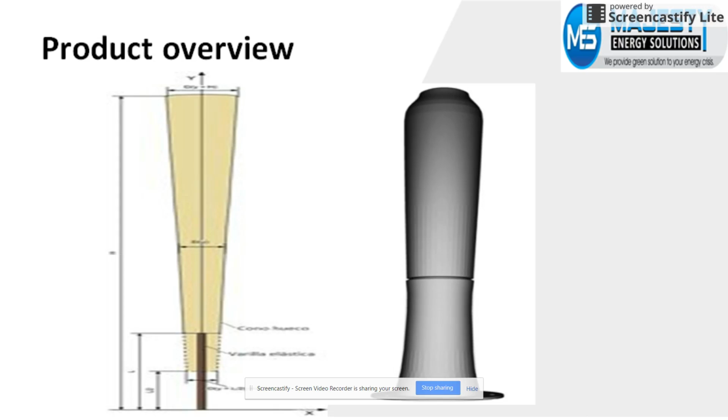The structure is built using resins reinforced with carbon and/or glass fibers, materials used in conventional wind turbine blades. The inner cylindrical rod, which may penetrate into the mast for 30% of its length, is anchored to it at its top and secured to the ground at its bottom part. It is built with carbon fiber, which provides the highest resistance to fatigue and has a good mechanical quality factor, allowing its elasticity to absorb the vibrations generated by the cylinder.